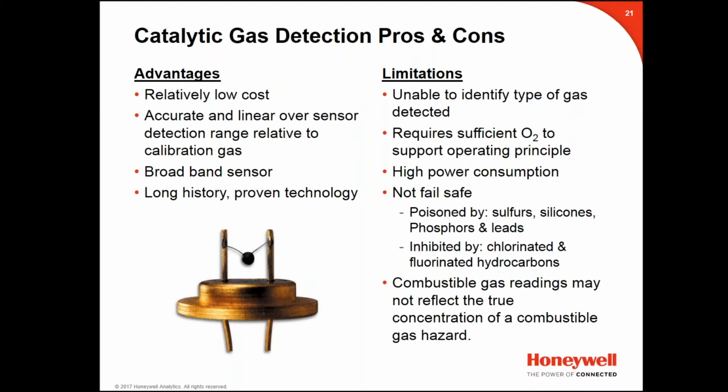It has a high power consumption. Sensors are vulnerable to being poisoned, and combustible gas readings may not reflect the true concentration of the gas hazard that's present.